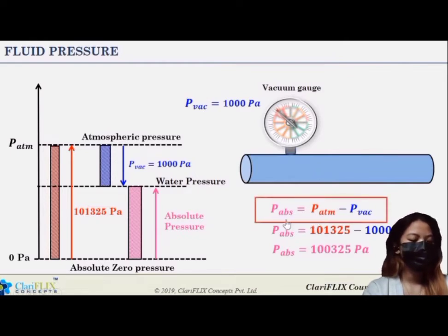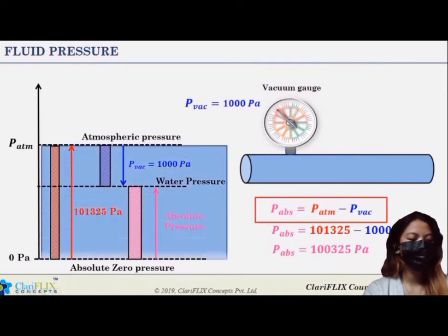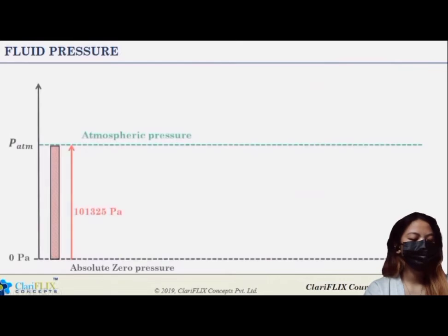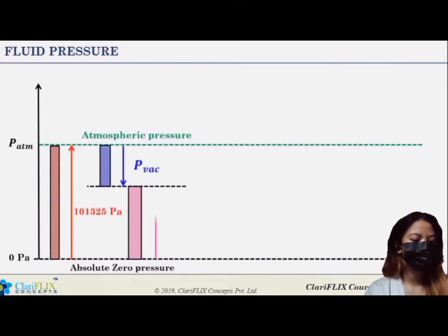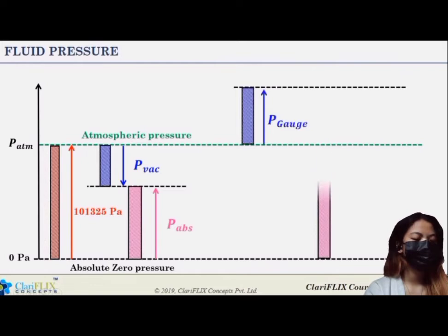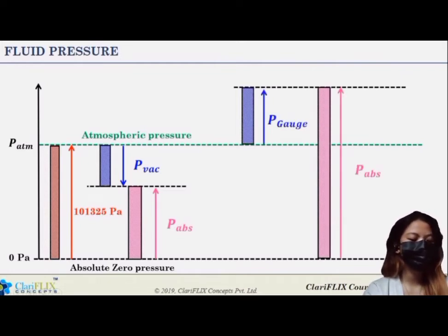Now again, this equation can be used to convert pressure from vacuum pressure to absolute pressure or vice versa. Vacuum pressure considers atmospheric pressure as the reference line and measures the pressure accordingly, but unlike gauge pressure, vacuum pressure is specifically used for representing pressures which are lower than atmospheric pressure. The beauty of gauge and vacuum pressure is that you can easily feel and realize the fluid pressure from their values, as they are measured considering normal atmospheric pressure as the reference.